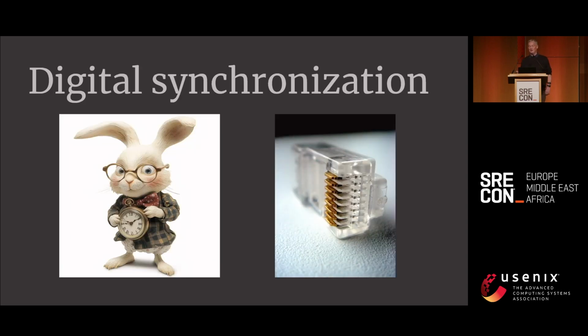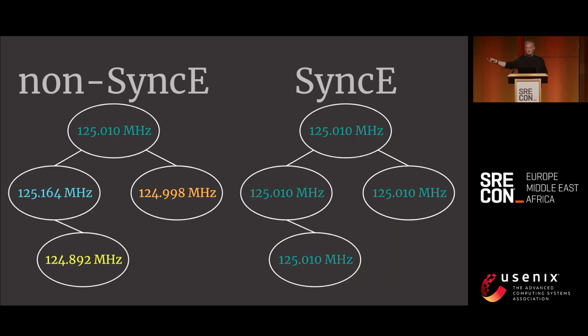Now we know the various ways to read the clock, but how does synchronization work across the network? Lena's talk later today will cover this aspect in more detail, but I'd like to focus on a technology which might be new to you, named White Rabbit, or more boringly, Precision Time Protocol over Synchronous Ethernet. In this simple network on the left, each transmitter uses its own crystal oscillator. Gigabit networking doesn't have a separate clock pin, so each receiver uses clock recovery to read incoming data. But wait, these nodes are continuously connected and able to track each other's transmit frequency. What if we defined a hierarchy from reference clock down to ensure all the oscillators throughout the network were aligned? This is the idea behind synchronous Ethernet. The nodes are not free-running, but instead follow the upstream node's frequency.